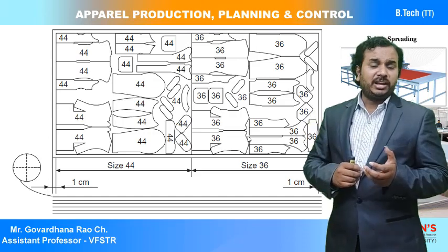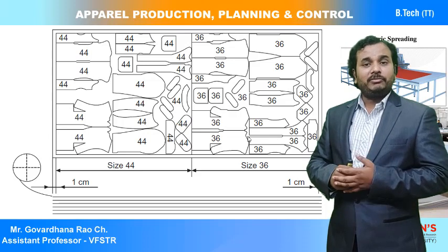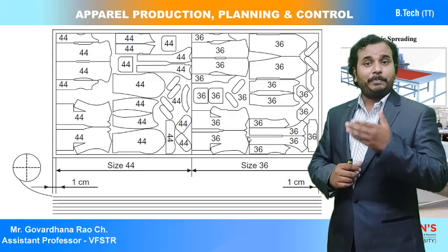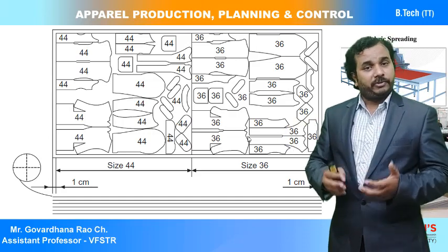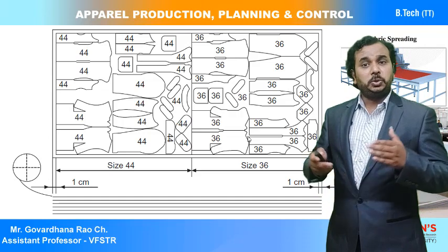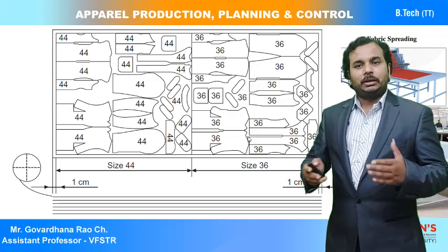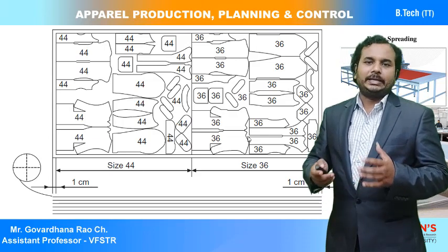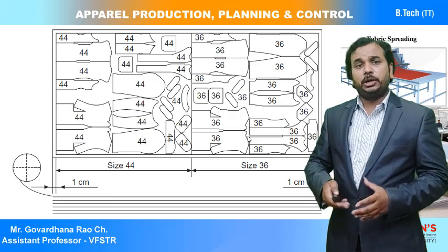Sometimes what will happen is, if the marker is displaced while cutting, the edges of the patterns are going to come out defective. That is why we need to leave some space, so that the patterns will be cut exactly.